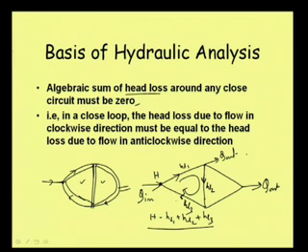But we know one point, that in any water distribution system, at a particular section or at a particular point, there cannot be two different heads. At a particular point, the energy level should be the same. So, now what will be the condition? Say from this point we are starting with an available head of H, and then when we are returning to this point we are finding that the head available is this much. That means that the head loss, what we are considering to be as loss, this must be equal to 0.